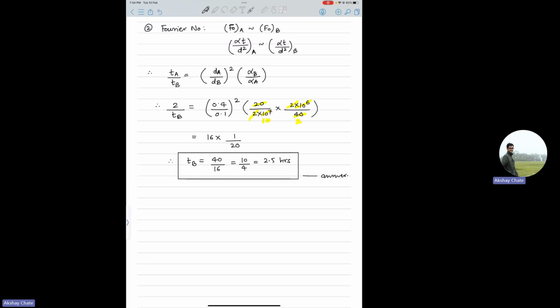Typically, a valid similarity solution will result in the reduction of one unknown variable, and the boundary conditions should be satisfied. Otherwise, that similarity variable is not valid. In the end, you typically end up with a governing equation, some sort of ODE or PDE, linear or non-linear. It can be anything, and you typically need numerical methods to solve those equations.